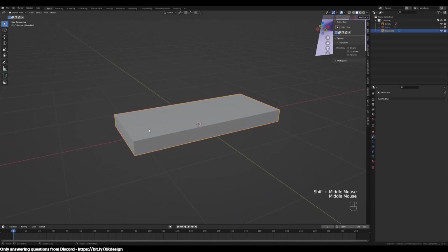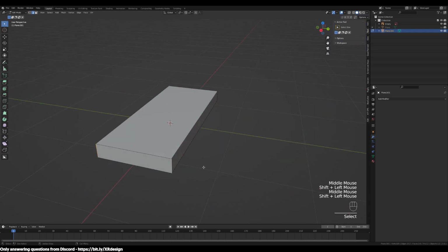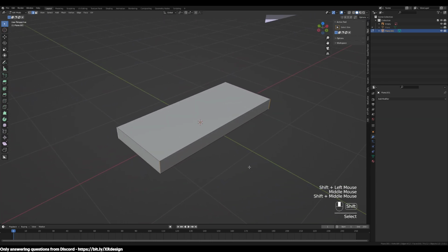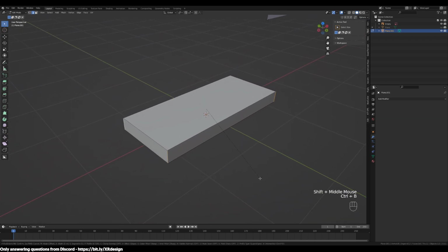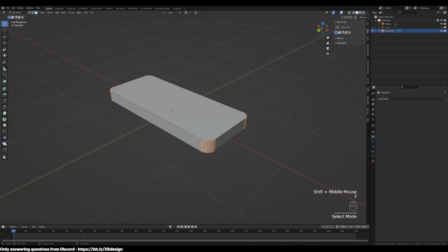And we're gonna select the object, hit tab, and just select those four corners with the edge select tool. Okay, and then hit Control B, and we're also gonna round it by 5 faces by this much.